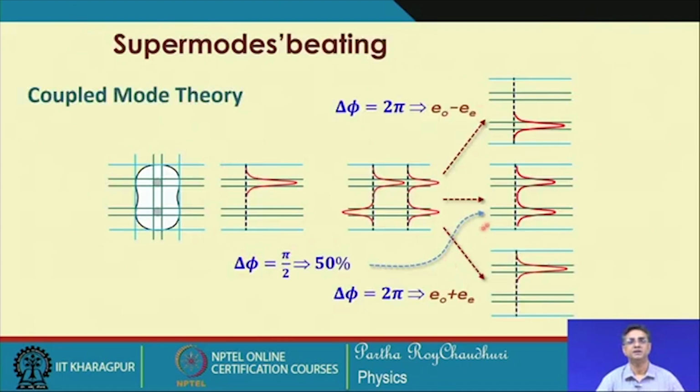To understand the same thing in the case of an optical fiber, you have a core here, you have another core here, and light is launched into this waveguide. At z equal to 0, consider that this mode in the first fiber is a combination of the two lowest order super modes, that is, the normal modes of the composite, total structure.